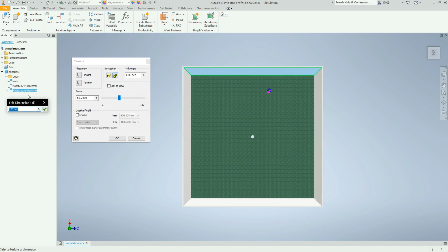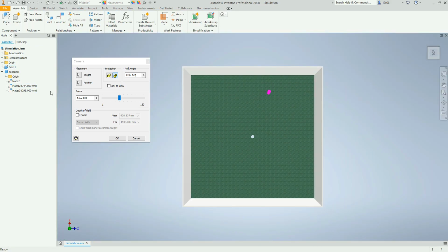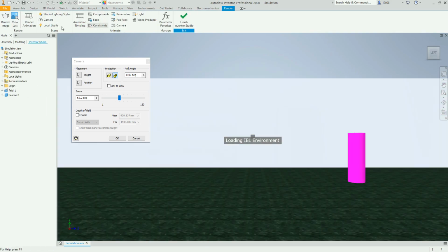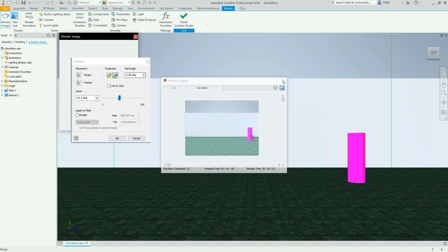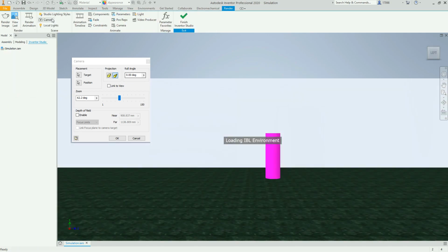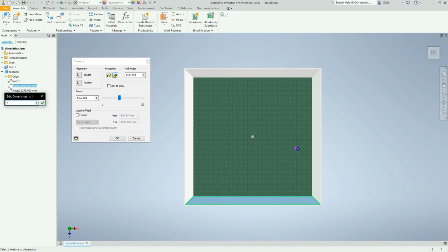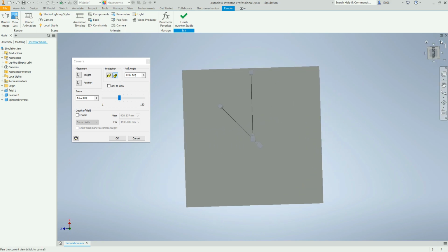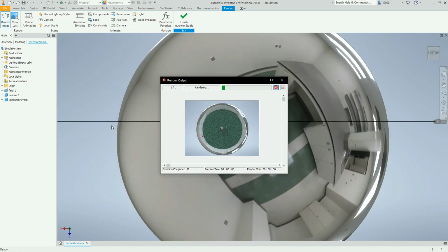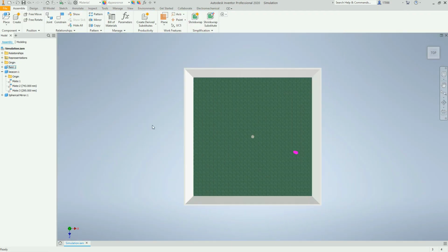The beacon was placed at 7 different angles: 0, 5, 10, 15, 20, 25, and 30 degrees for both camera systems to observe. A constant distance of 750mm was used to separate the beacon from the camera. The 360-degree camera system was also subjected to 45, 60, and 90-degree tests to determine if there was a pattern to the error found. Note that the 360 camera angle test extension only goes from 0 to 90 degrees. This is because the spherical mirror will have the same error around the 4 quadrants in their relative places.